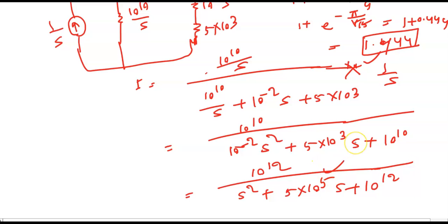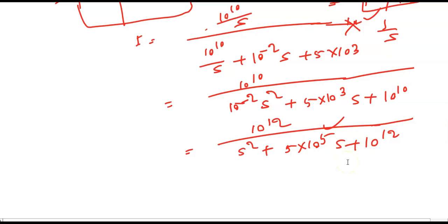In this step, if you could identify that the question is from the underdamped case, and it has been asked for the maximum value, then we need to calculate the maximum peak value, multiplied by 1 upon s, then add 1, so that we can get the maximum reading of the ammeter. Then you can easily get it. Otherwise, you obviously need to think smartly in the GATE exam,